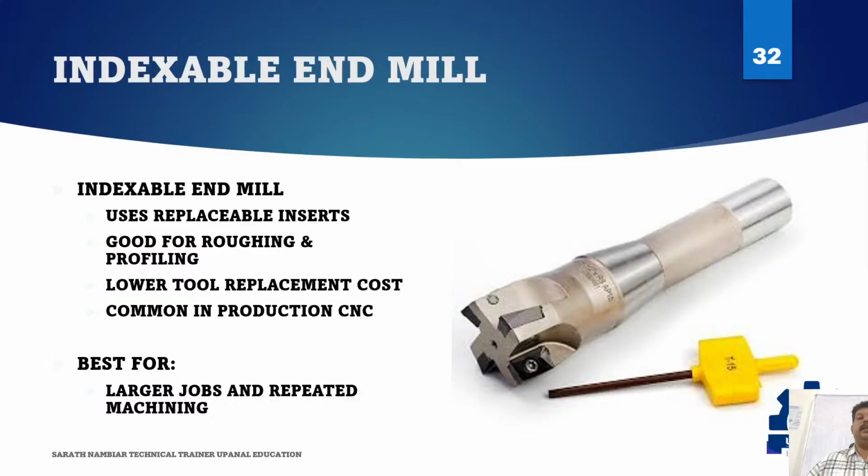Indexable end mill. This cutter uses replaceable inserts instead of a full solid carbide body. That means when cutting edges wear out, inserts can often be replaced while the tool body remains in service. Why is this valuable? In precision machining, cost control matters. For large diameter tools or repeated jobs, replacing inserts may be more economical than replacing complete solid tools.